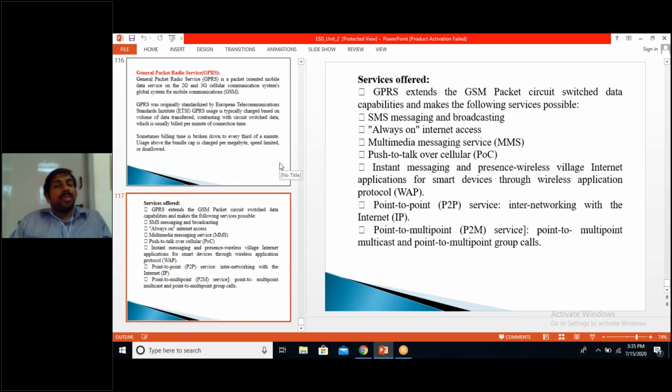So coming to our topic, the elements of an embedded system. We have a sensor to detect; it is a transducer which converts a physical quantity of any type into an electrical signal. Actuators convert electrical signals to physical actions. These are connected to your core. That core can be any hardware: general purpose, ASIC, PLD, or COTS, commercial off-the-shelf components. And this is connected to your memory, which is of two types, RAM and ROM. All these are connected by a wired network called the onboard or board level interface, or this embedded system is connected to the external world by wireless or wired techniques, such as the communication interfaces provided.